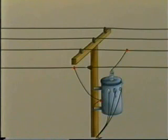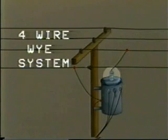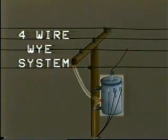If the primary system is solidly grounded, for example, in a 4-wire Y connection, then the tank of the transformer can act as the grounded neutral. In this case, we need only one high-voltage bushing on the transformer, connecting one of the terminals to one phase of the primary feeder. The other high-voltage winding terminal is connected to the tank, which is in turn grounded externally. A ground connection should be made to the spade lug located on the tank.